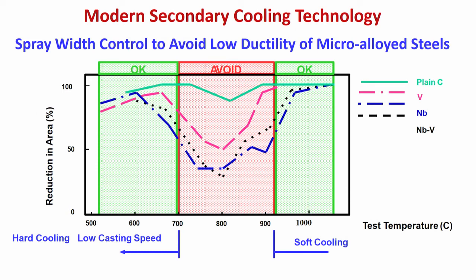It will lower the surface temperature of the strand, and because the temperature inside the molten steel is high, there will be a heat path from inside, and heat will come out. So, this is dictated by the surface temperature. Now, the intensity of cooling and the uniformity of cooling, I have told you several times, are very important.